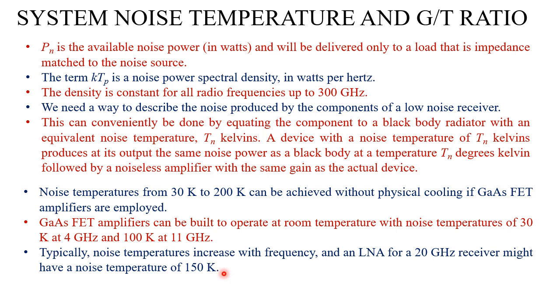Okay. See, higher noise temperature means it is generating a high amount of noise. Simple as that. So our objective should be to keep the noise temperature as low as possible. And noise temperature is actually related to the noise figure of the system.